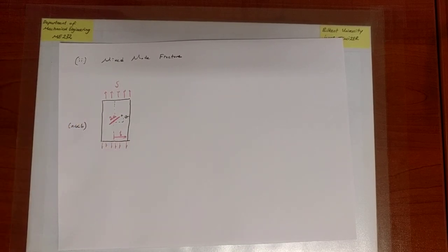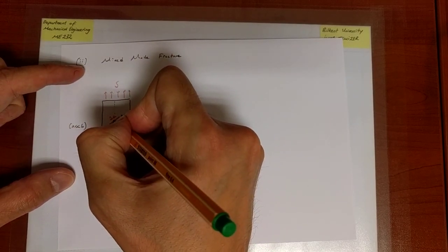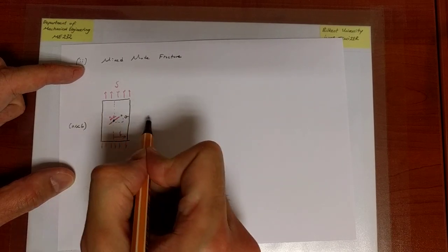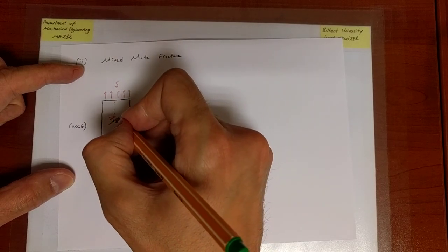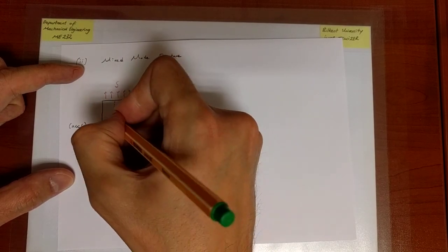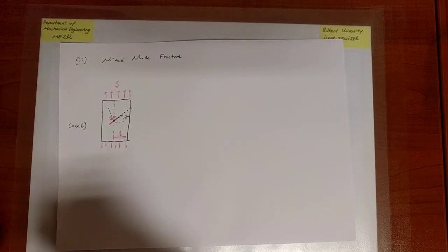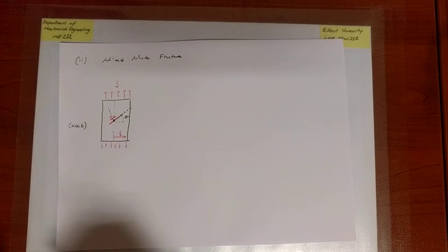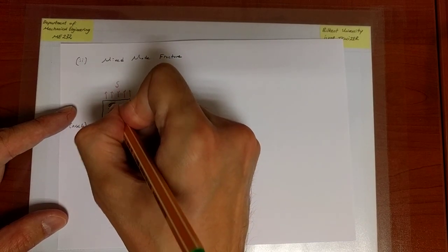So, well, what do I do, right? Well, what you can do is, again, decompose this problem into two parts. What I know, and this is an application of Mohr's circle, is that at that point you have a state of stress with respect to our convenient coordinate system, which is a normal stress in that direction. But if I choose a different coordinate system, or I'm looking at a rotated plane which naturally aligns with the crack, there will be different components of the stress, which I can calculate from Mohr's circle. In particular, in general, there will be a shear stress, and there will be a normal stress.